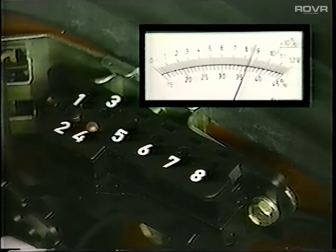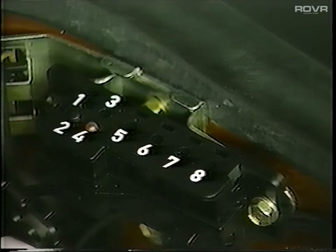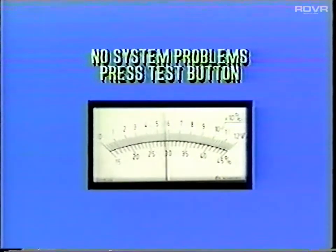If no fault codes are stored in the system, the LED will blink once. If the LED blinks more than once, do not proceed with a lambda on-off ratio test. You must first correct any problems that are present in the system. When there are no problems and only one blink is observed, you may proceed by pressing the button again for 2 to 4 seconds. The CIS-E control unit is then programmed to send the on-off ratio signal.